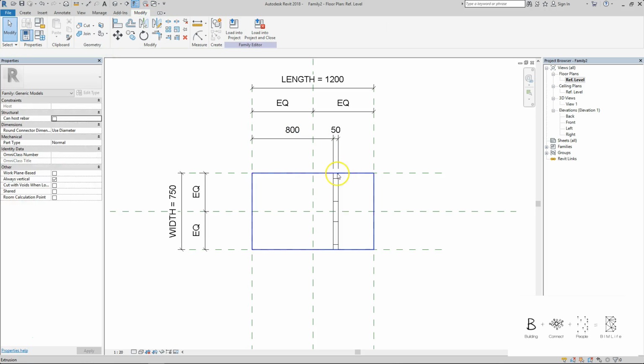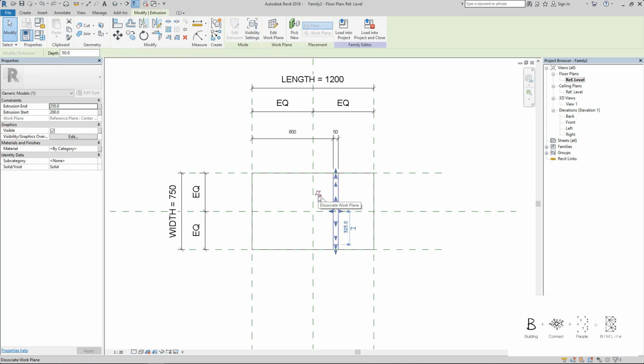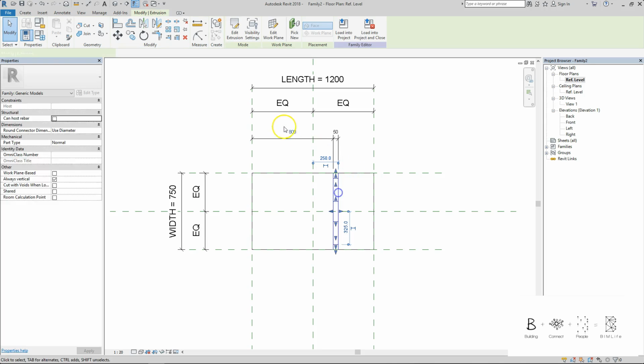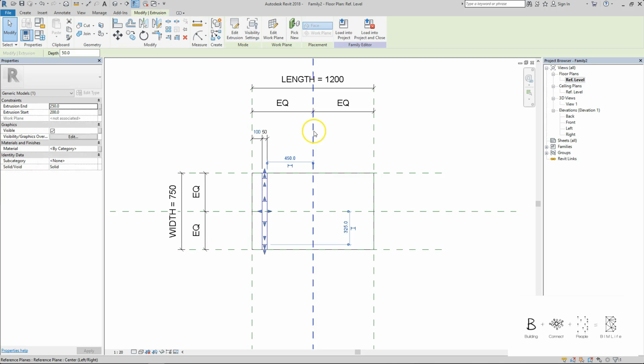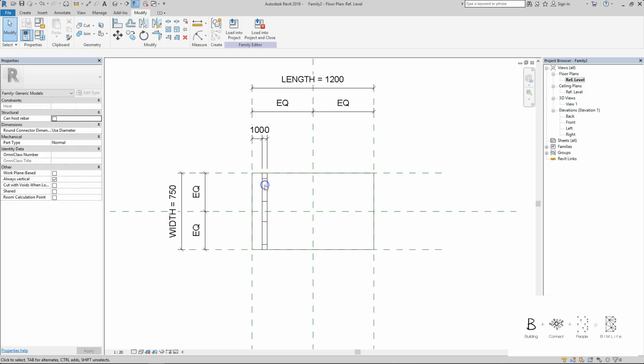So you notice that you can't move this when you select the object. You need to actually click on the object and click on the associate work plane so that it can move horizontally on the horizontal axis. So click on this and then click on the object again. You should be able to type in 100. Just lock the 100 because it's again not parametric.